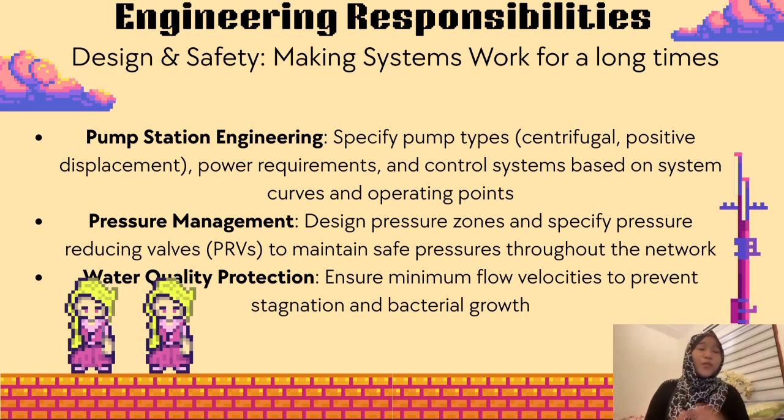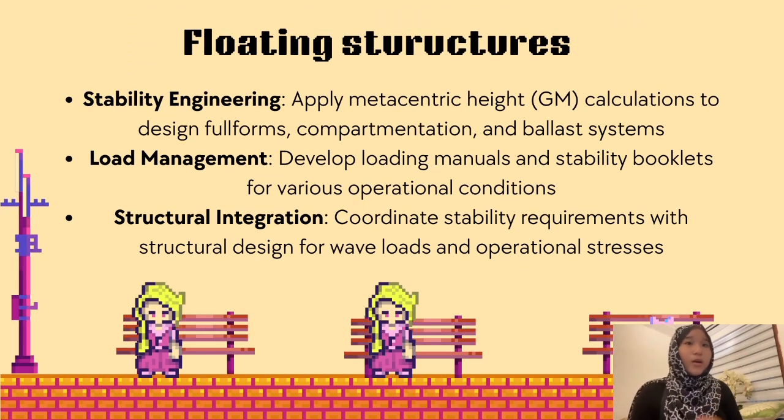So there's also floating structures, which I just mentioned just now. There's three key points under floating structures, which is stability engineering. So it's apply metacentric height GM calculation to design hull forms, compartmentation, and ballast system, like I mentioned before. The second key point is load management. So develop loading manuals and stability booklets for various operational conditions. And lastly is structural integration, which is coordinate stability requirements with structural design for wave loads and operational stress.